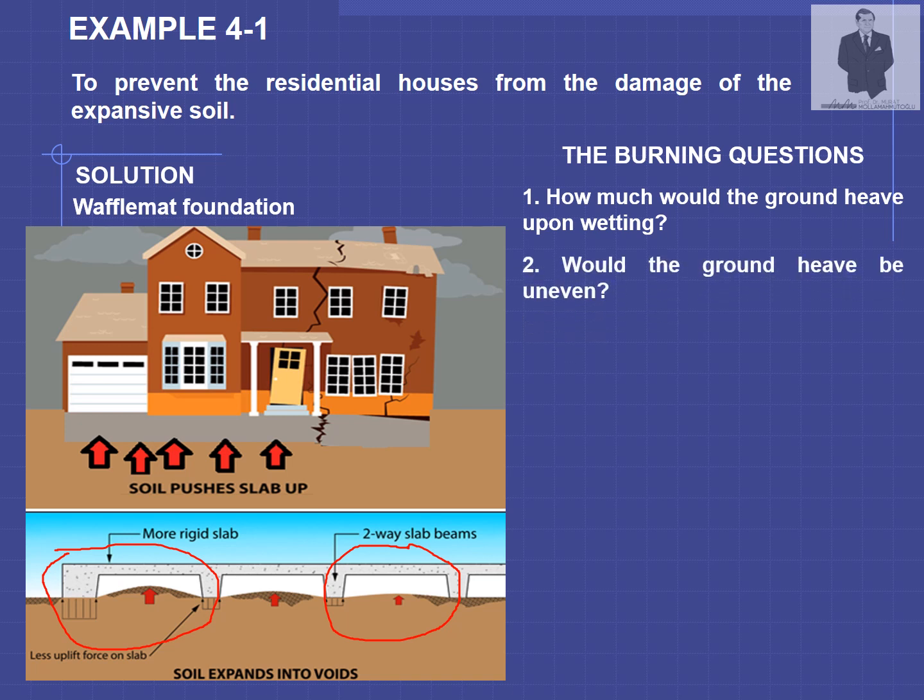The second question, would the ground heave be uneven? An important point, because when the uplift pressure concentrates in some part of the building, as shown here, then there will be a differential movement. This will cause the building to fracture.